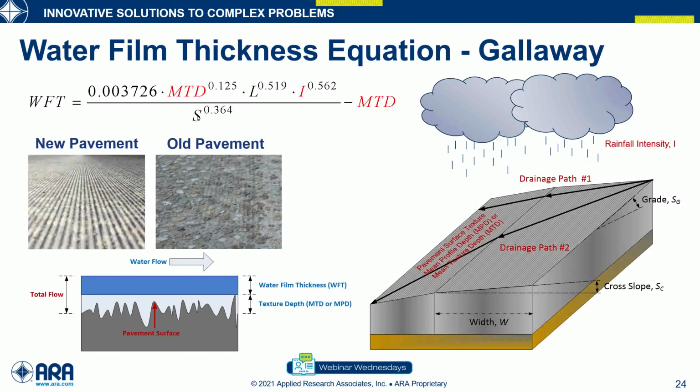That allows me to mention another function that this tool has. You can output a KML file and you will be able to see the cross slope, the grade, the hydroplaning speed, and the waterfall thickness on the actual road. So you can, as Brian said, overlay the waterfall thickness and hydroplaning speed with your crash diagram. And sorry, what was the other part of the question?